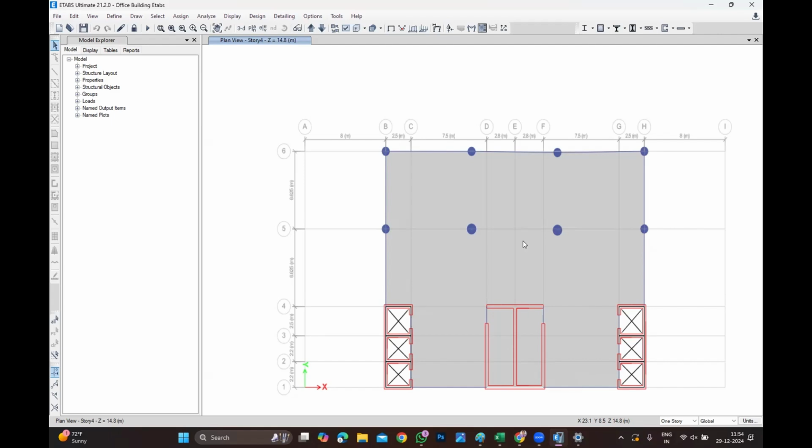The reason why in a rounded section you are taking 1.2: when you are calculating the wind in terms of the dynamic pressure, you are not taking half of the section, you are taking the full section. So it is a bit conservative; they're asking us to multiply 1.2 times the dynamic pressure.